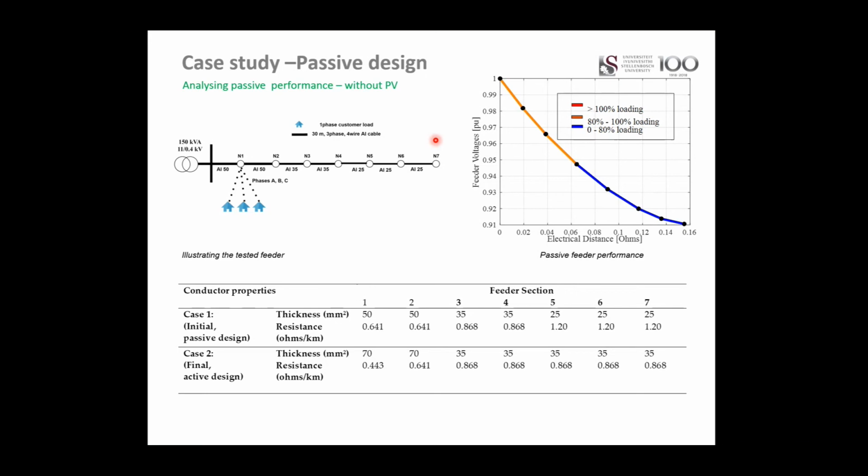So you can go back to your overloading characteristic, which is probabilistic, and say I can allow so much, based on the feeder characteristics, that probabilistic line rating. If you can put that into all of this, then in your background you've got your feeder being probabilistically modeled in terms of its capacity.